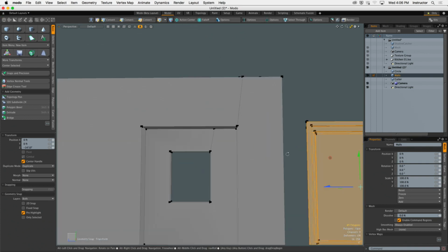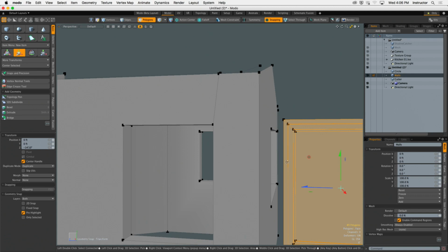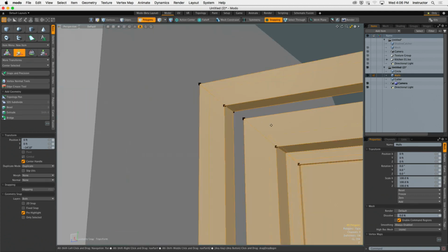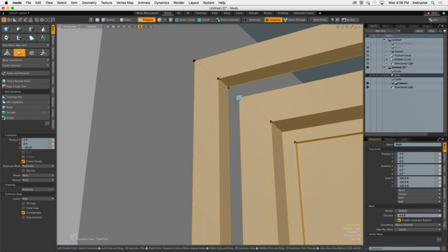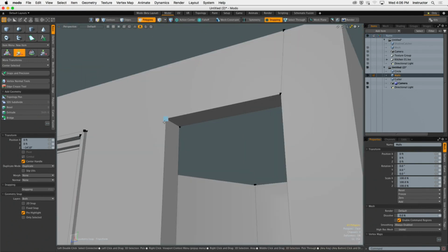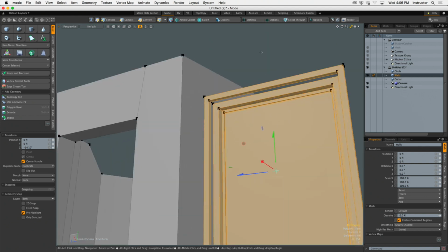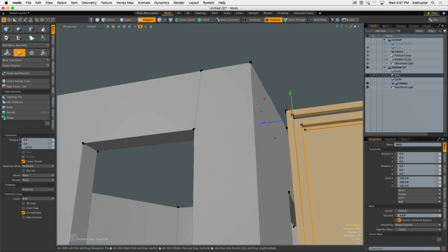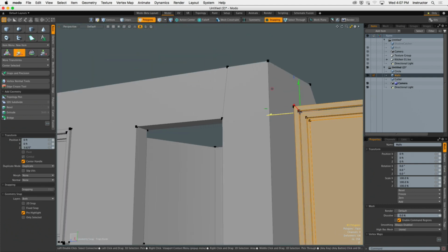But now I need to figure out where this window goes in the box over here. And this is where it hurts your brain a little bit. But that inside corner of my window should go right there inside the box. Well, while the snap is on and my action centers are off, I can snap my tool handles to any vert in my scene, right? And with my tool handles snapped to that vert, I simply can drag over.